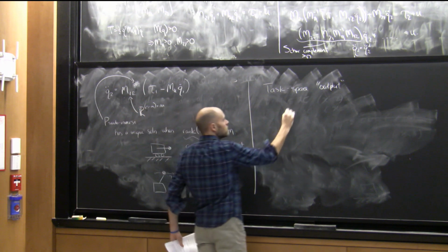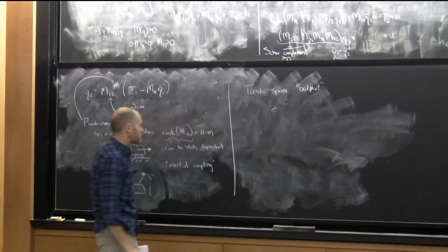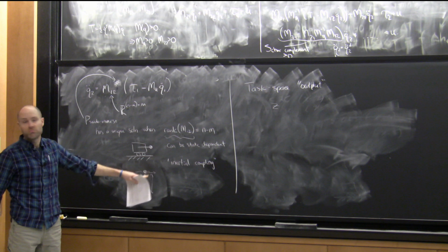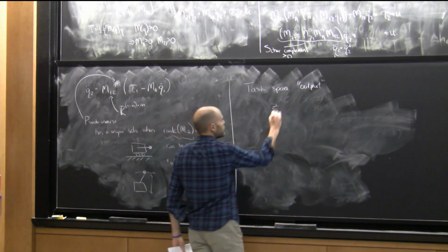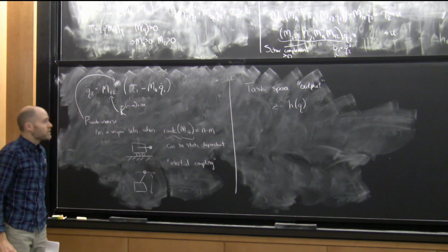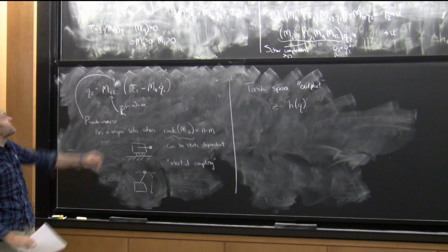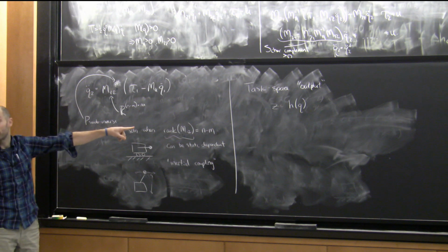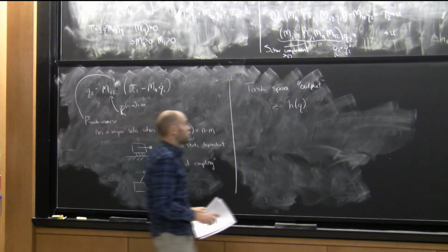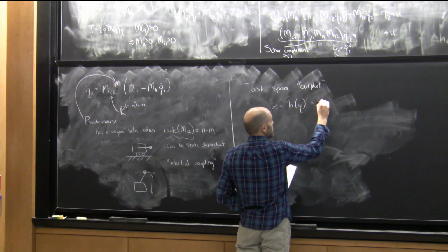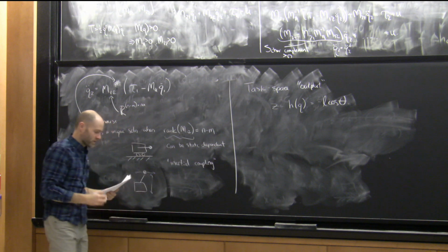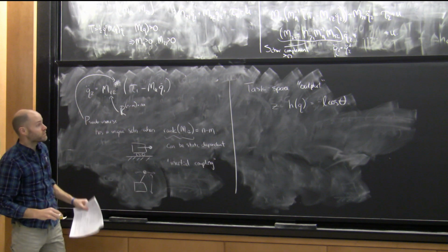All right. So let's make some new variable z, which could be, for instance, the vertical position of the end point of the pole, or something like this, which is some function h of q. Certainly, if h is just picking off q1 or q2, then that's just a special case of this. But it's more general in the sense that I could do, for instance, let's say in end effector space, the end effector dynamics of the endpoint of the pole.